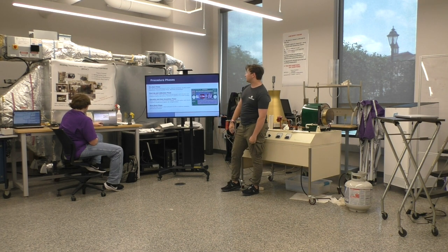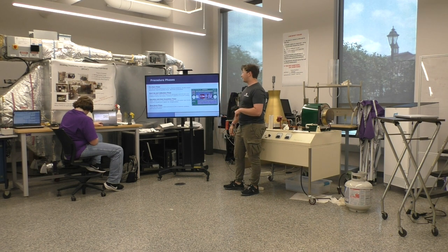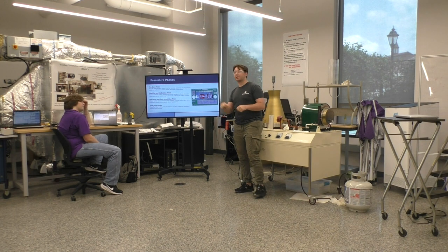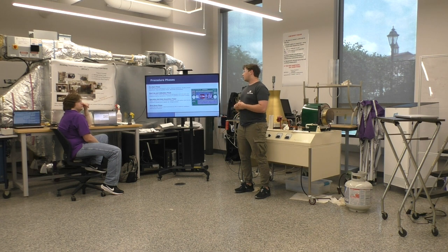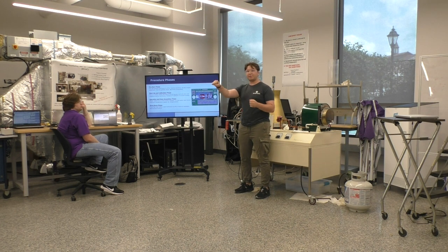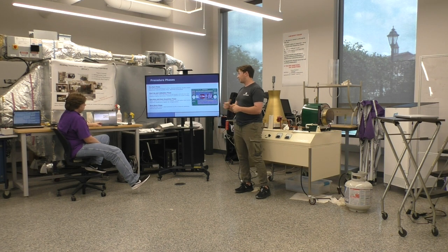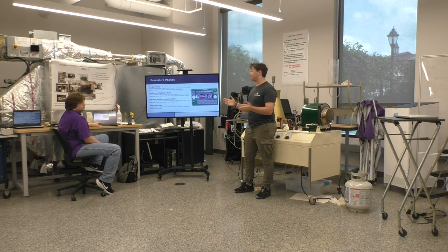But next, there are a lot of procedures during this experiment. So I just broke them up into phases. In the pre-start phase, you're just putting everything to the base start level, where you want to visually inspect the equipment, make sure all the levers work and that it's connected electrically. For the startup calibration phase, you're going to turn on the master switch, see that everything's lighting up, move the levers, see if they work or if they're obstructed. Then for the actual operation, you're going to do everything, but this time press the start button, run the experiment, gather the data acquisition, and then for the shutdown phase, you're basically going to reset everything as you found it.